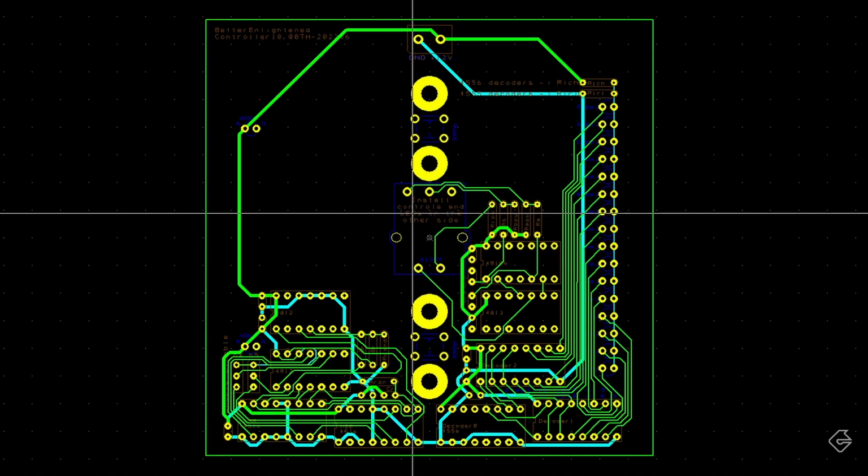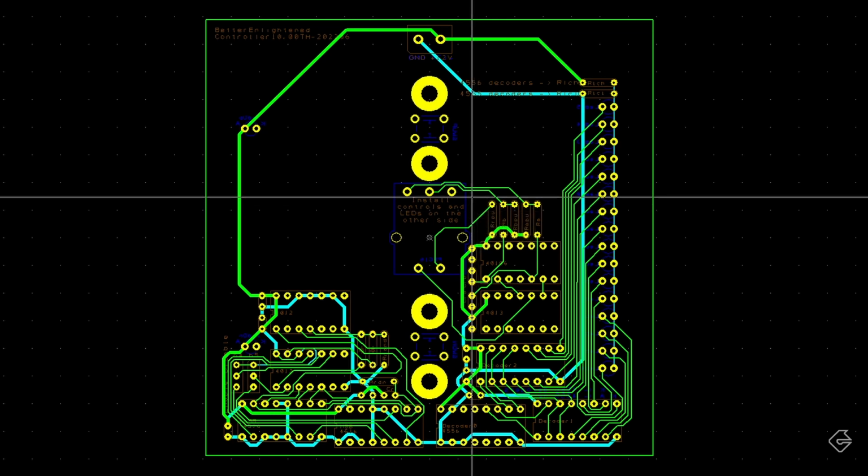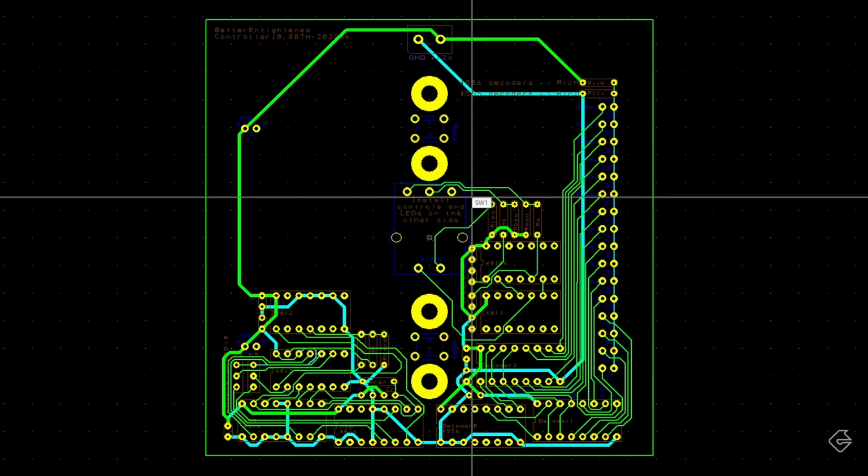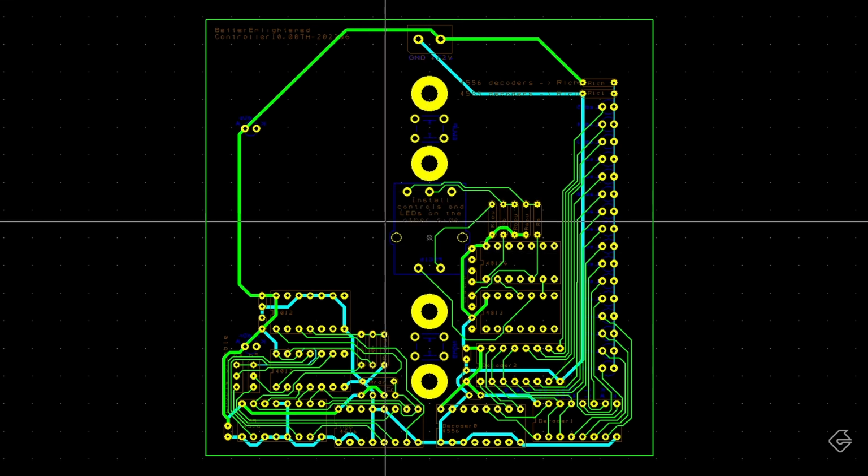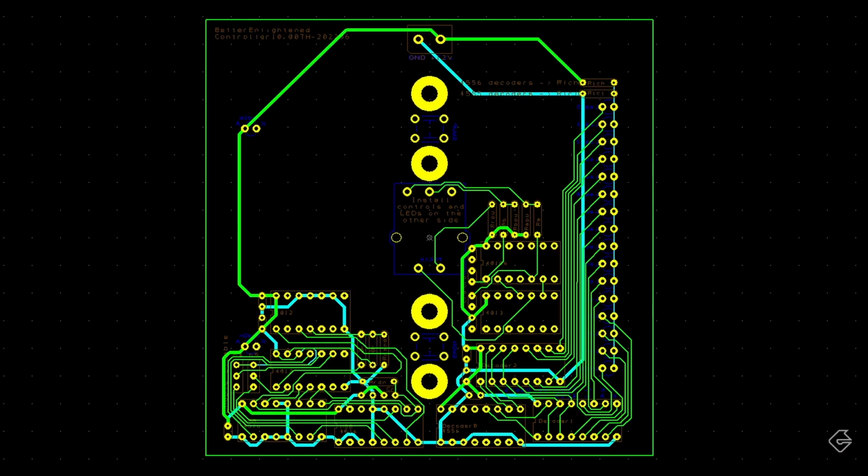When we actually build this, there's a choice between buttons or rotary. If we have the rotary encoder, we're not going to use the buttons. If we're going to use the buttons, we're not going to use the rotary encoder. Although the circuitry will be there, there will actually be no physical rotary encoder. We're not going to connect this in, which means there'll be an empty space over here. So perhaps I can put my reset button in that empty space, therefore making use of all the space on the board. There it is.